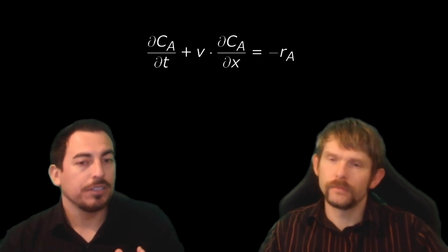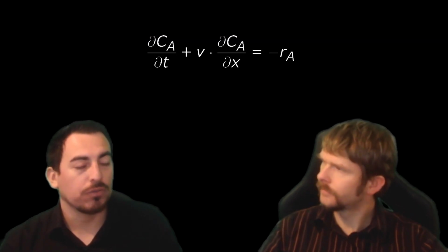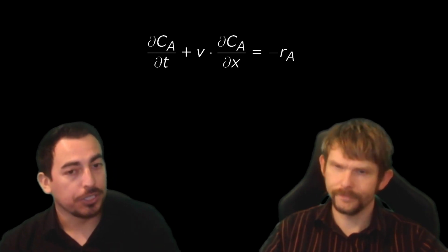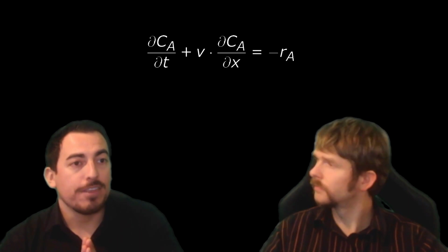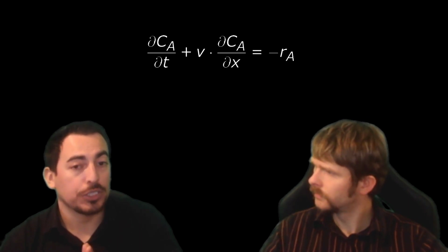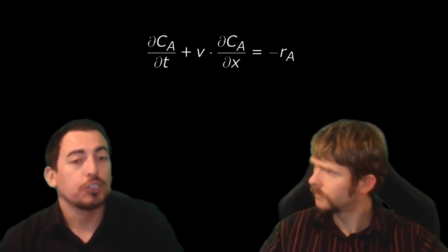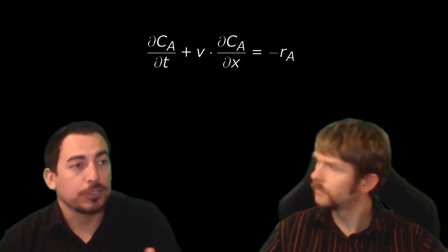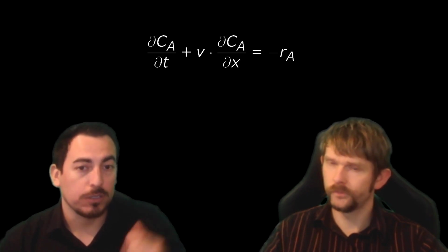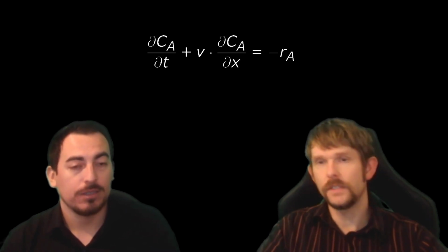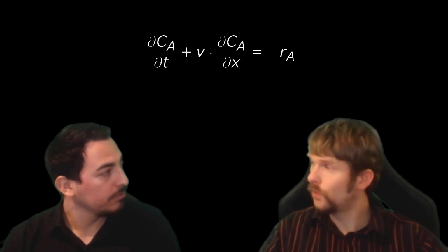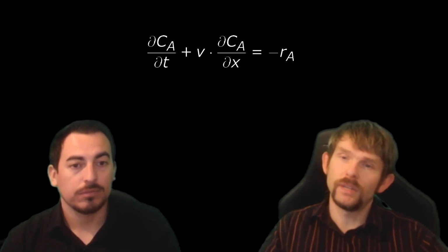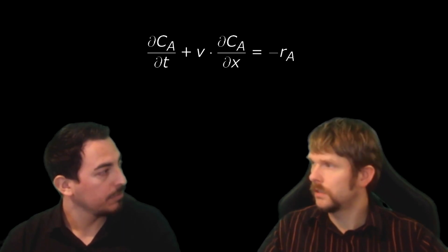Okay, so here we have a partial differential equation for the system, or for any system in general. We neglect the first term with the first derivative, and with that we assume the concentration doesn't change with respect to time. So the system is in equilibrium, and we can't simulate the startup or shutdown processes with this simplified model. Alright, that just means the left term disappears. We assume there are zero changes over time, but there are over the length. But what about the velocity, the right term?